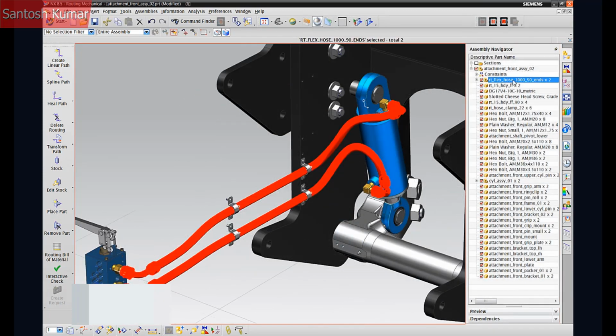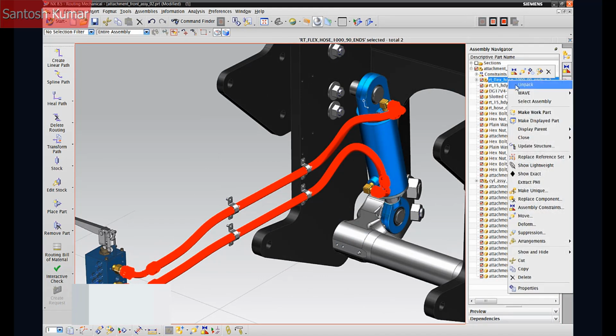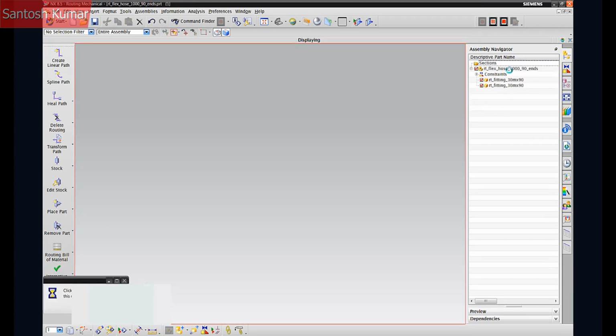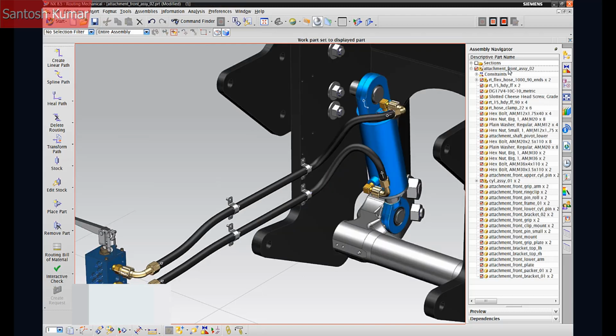Even though both components appear to be different shapes in the assembly, they are the same component and would report as 2 off by 1 metre hoses in the bill of materials. The component itself is not modified, the modification is for that assembly instance only.